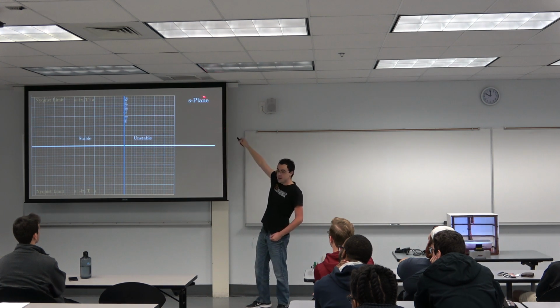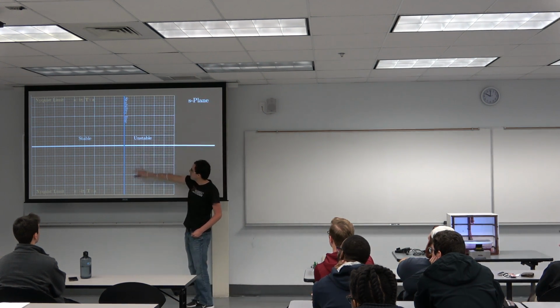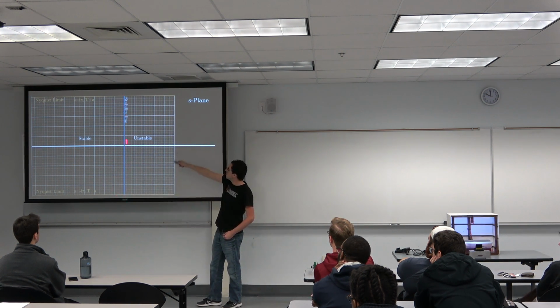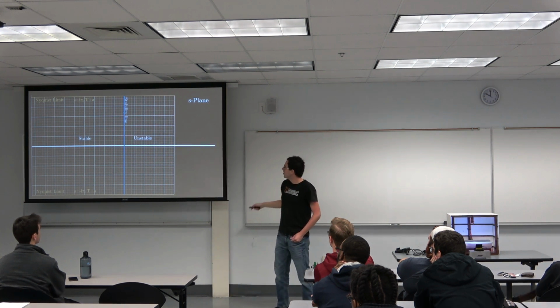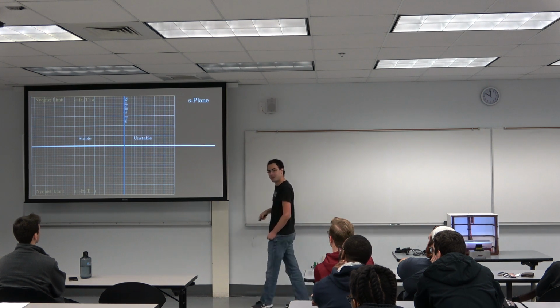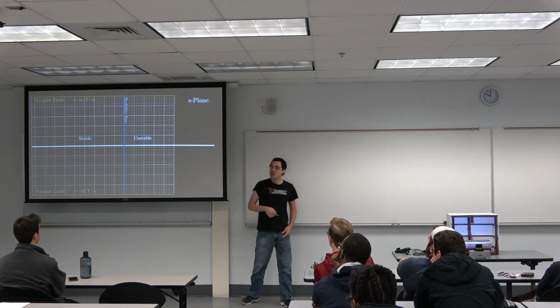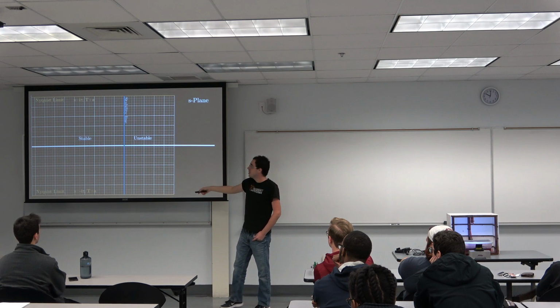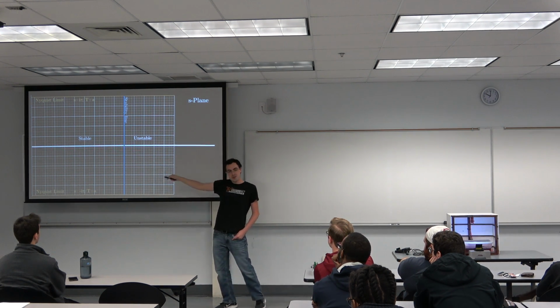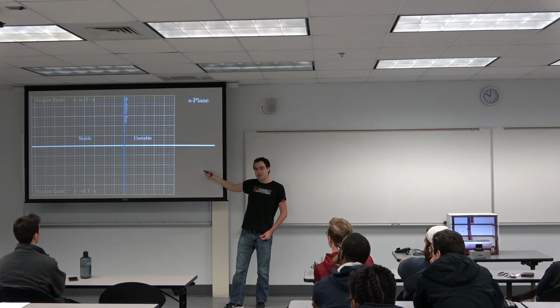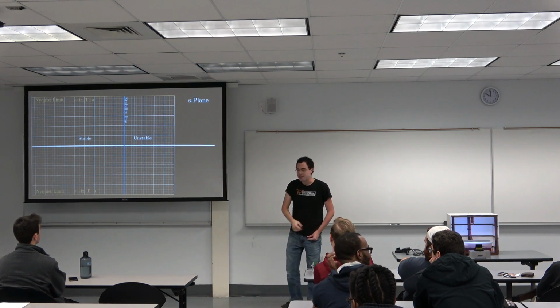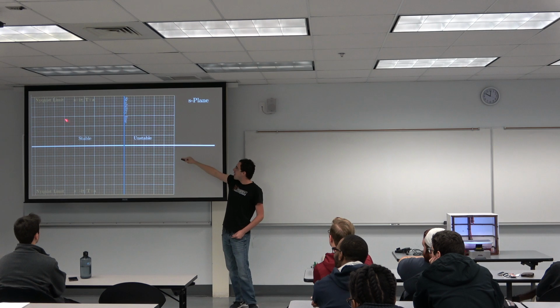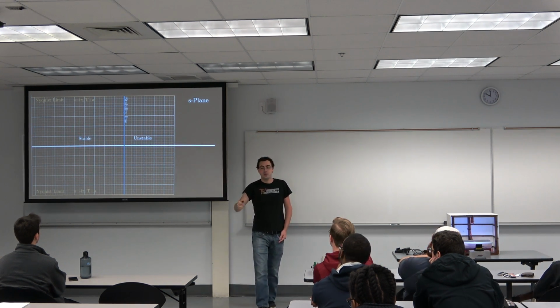So here I have the S-plane, and I have here just a little bit of the plane. This is the imaginary axis. This is the real axis. And maybe you can tell me what happens when I'm in the right-hand side of the plane. It's unstable. If I'm in the left-hand side, then I get a decaying signal or decayed sinusoid. If I'm sitting on the real axis, in the stable side, what do I get? What is that? No oscillation, exactly. It's just exponential decay. And if I have any finite complex number, then I get some oscillation, right?